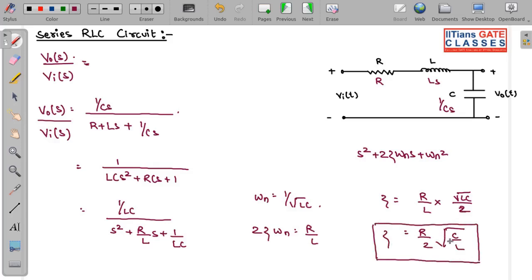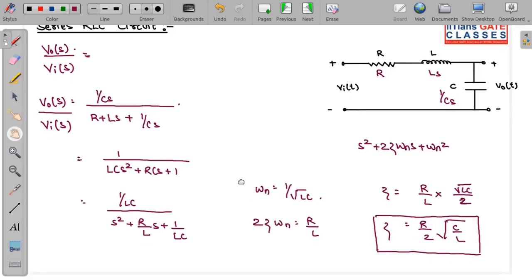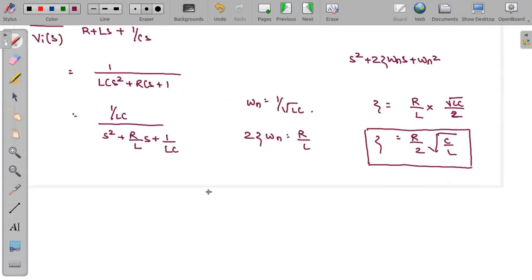Now by varying C, L and R, we can get different systems over here. Okay, you can get different systems over here. Now there is one more thing known as quality factor. Okay, quality factor. Now what is this quality factor? Quality factor is equal to omega naught L by R, or it is equal to 1 by omega naught RC, whichever you want to apply.